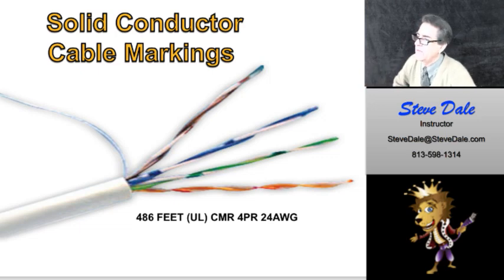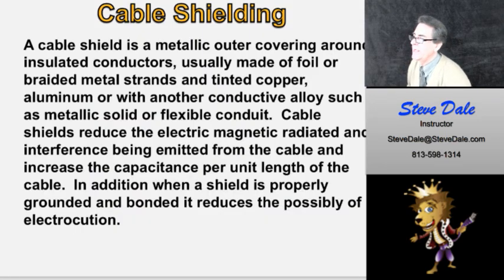Solid conductor cable markings here. These are twisted pairs. The insulation is wrapped around each other. See that? They're twisted together to reduce crosstalk, right? This is 4 pair and 24 AWG. That tells me the gauge size and how many wires are under the insulation sleeve. All right, let me just briefly read this here.